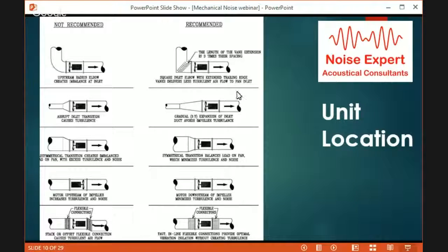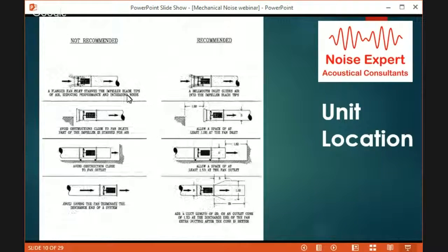Whereas if you have an elbow right next to it where all the airflow is slammed down on the lower portion, or there's dramatic transitions, or they're not equal, not symmetric transitions, or offset ducts, you won't be matching that. The flow will not be even. That'll be a problem. That's the problem with diffusers as well, and we'll get into that.